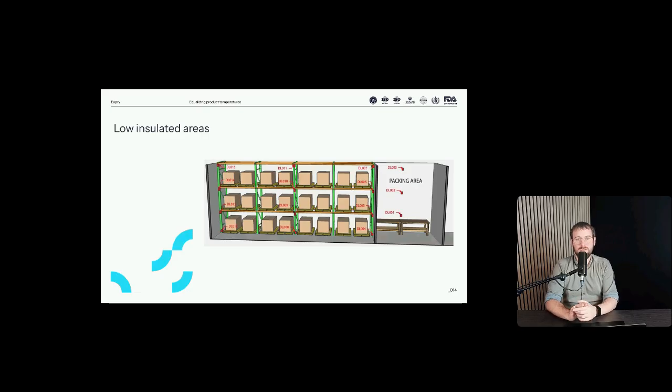But you also do have a degeneration of walls and floors and ceilings, where it's very important to find out whether that's a risk, and if you get data that it is a risk, act on it. It's not always that we can act on poorly insulated areas, but it is one of the things we need to keep in mind, that if we have transitions from different building elements, or we have doors and gates, windows, those areas will often be less insulated than other areas.